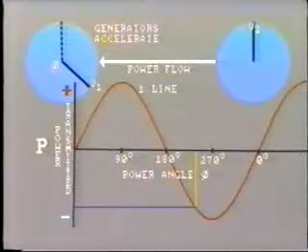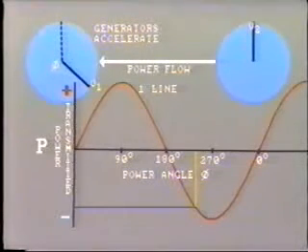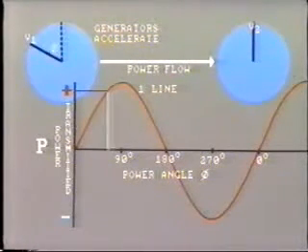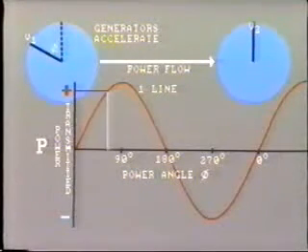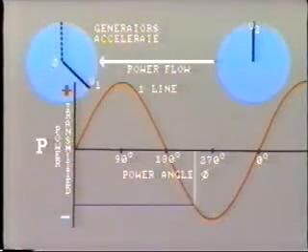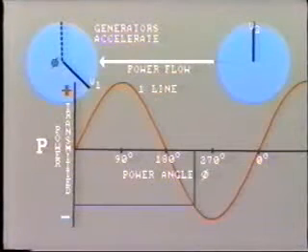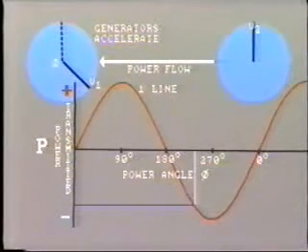This is instability. The reversal of power flow in this line will probably create large disturbances on other parts of the system. Hopefully, the generators at bus 1 will pull into phase and remain in phase as they recover their original position. However, experience tells us that this is not likely to happen, and the generator will probably continue to accelerate and remain out of step with the system.